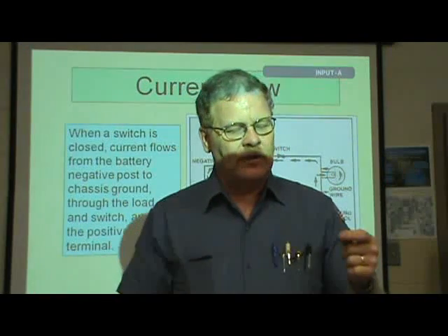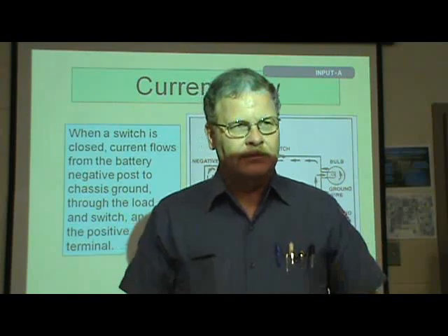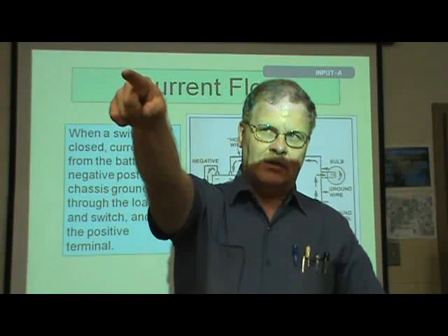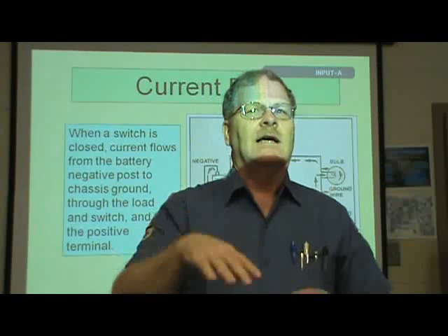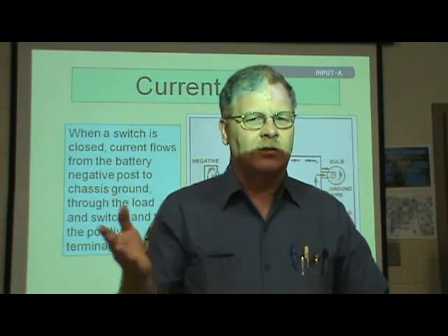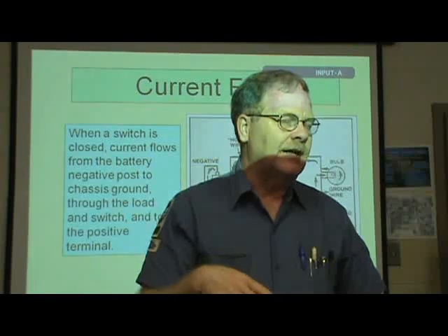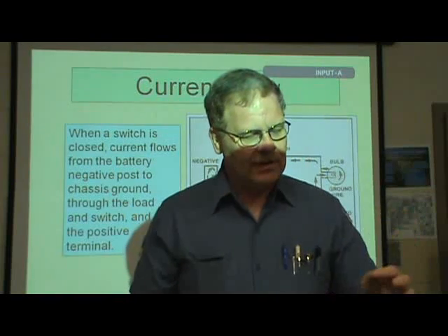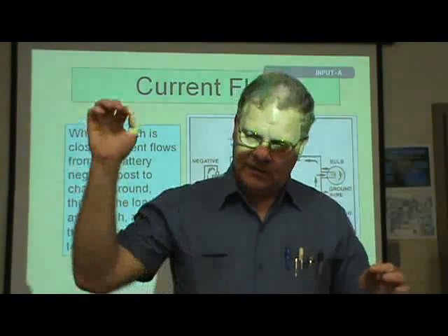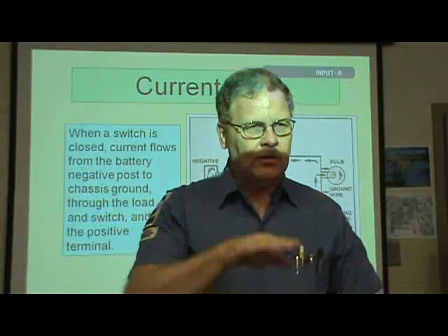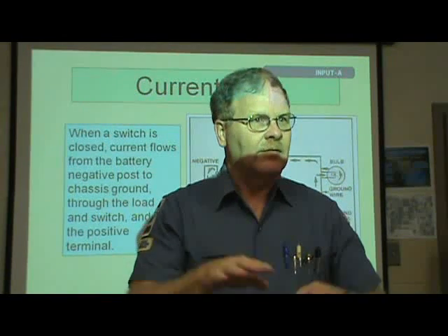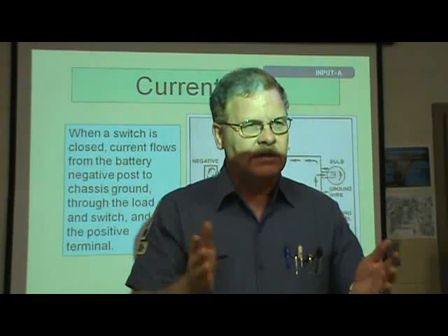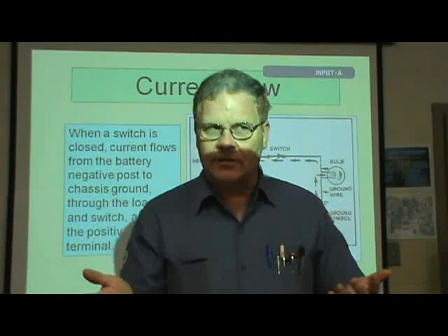If I know for an absolute fact that down on the other end of the car I've got a light that's dim, we can do voltage drop tests on the ground side and on the positive side. If we check from the positive battery terminal while current's flowing, and we go down and touch the other one, it's going to read a number. It shouldn't read anything if everything's like it's supposed to be. But whatever number it reads is how much we're losing. That's what voltage drop's about.